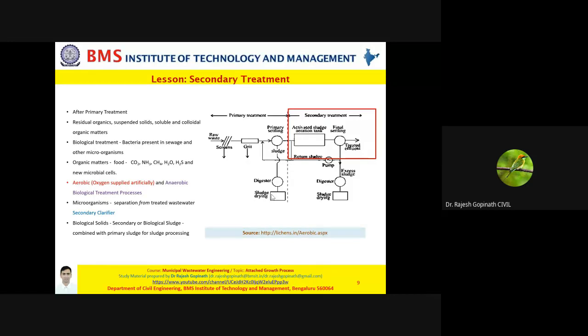So please remember one thing: in secondary biological treatment, trickling filters, RBC, biotower do not serve the function of allowing the sludge to settle. This settlement and removal of sludge all happens in the secondary clarifier, the sedimentation tank, which succeeds this treatment unit.